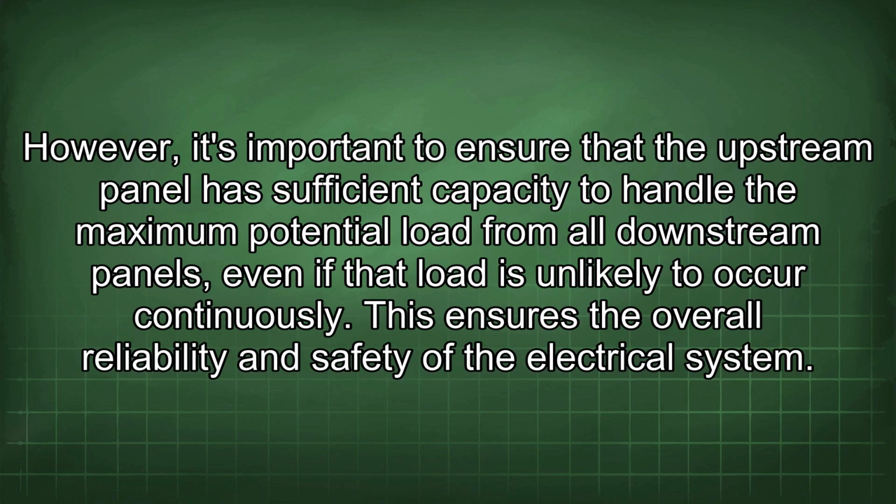However, it's important to ensure that the upstream panel has sufficient capacity to handle the maximum potential load from all downstream panels, even if that load is unlikely to occur continuously. This ensures the overall reliability and safety of the electrical system.